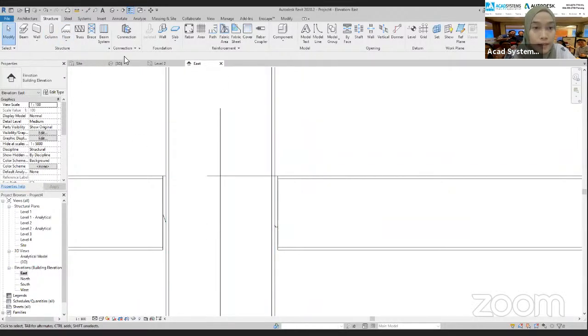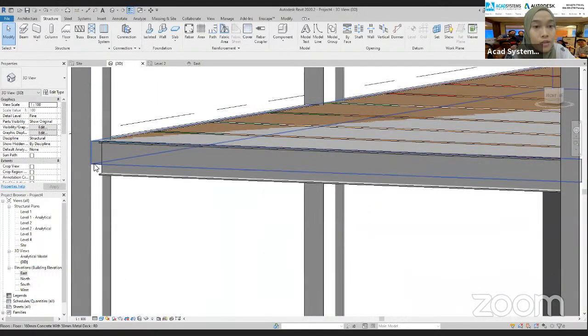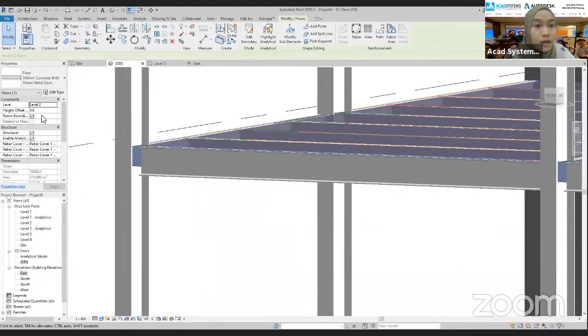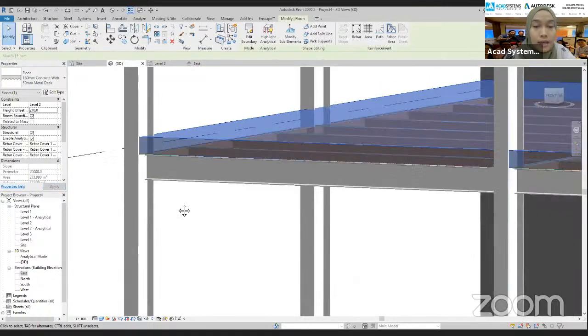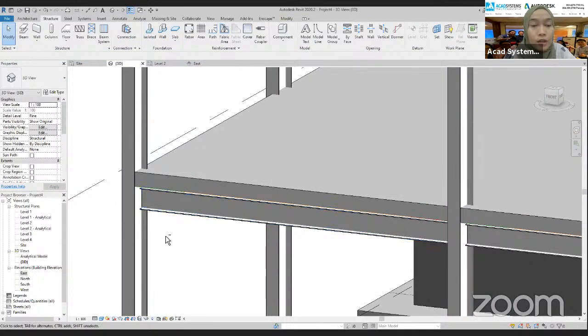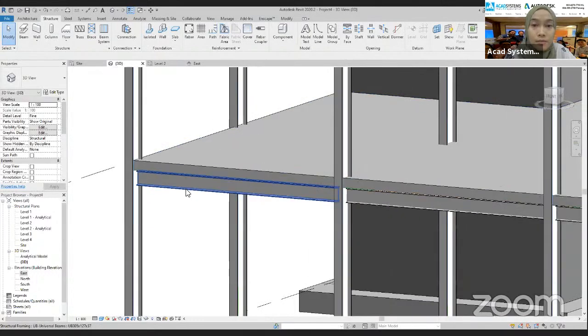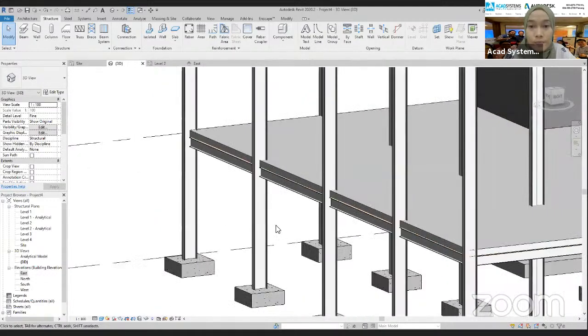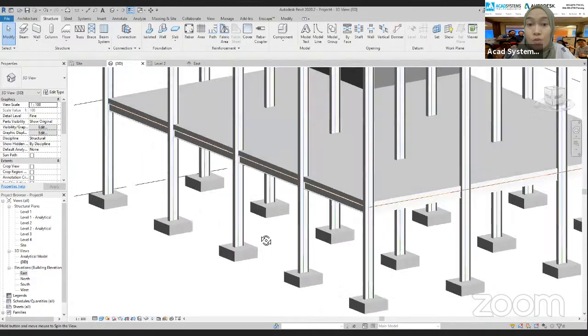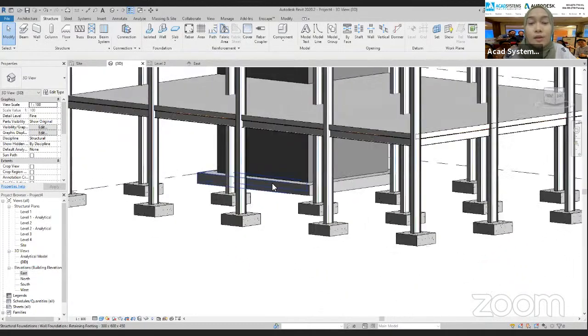So, all right, go back into our 3D and click on this floor. Okay. In the properties here, we have constraint height offset. So change it to 210. Let's click on apply, and yeah, we have our floor above our beam, so that it will not intersect or sit in our beam. Okay, so we're almost done with our model.